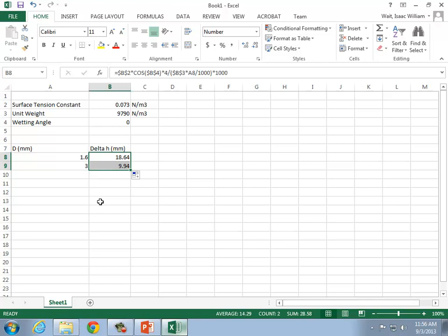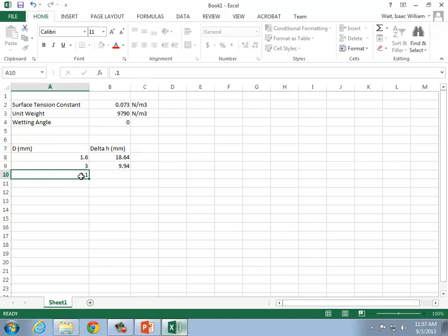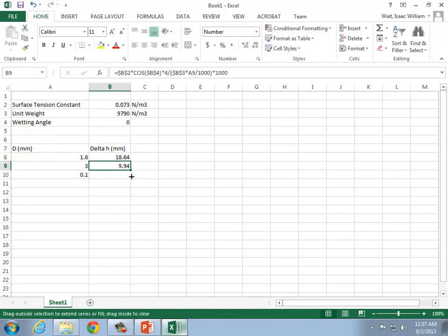If you look at the surface tension, if you increase the diameter, that'll increase the surface tension. But if you increase the diameter, you're increasing the weight of the water according to d squared. And so if you double the diameter, that will double the force that's going up, but it'll have 4 times as much water weight, and so it won't be able to rise as high. And so consequently, if you have maybe 0.1 millimeter, then the water is going to rise very high.